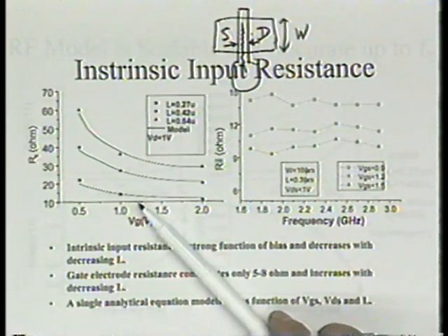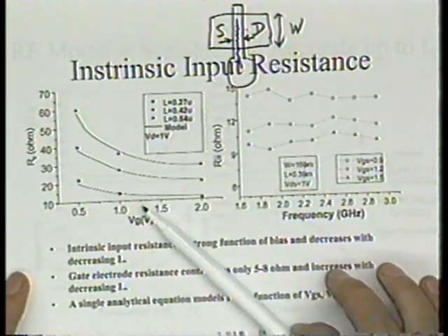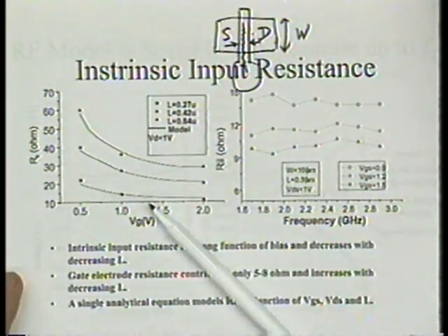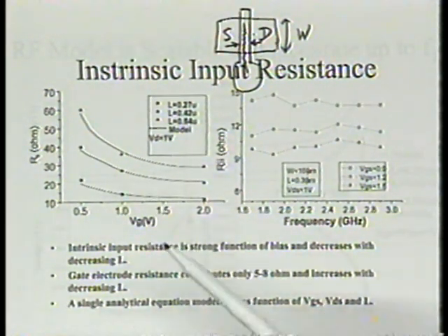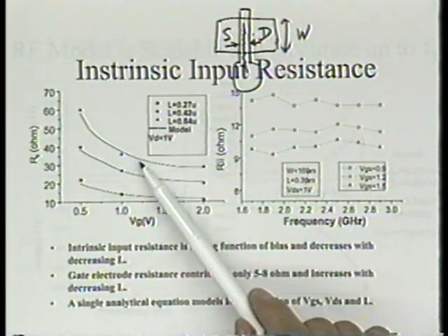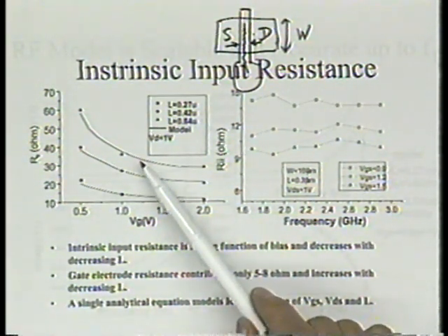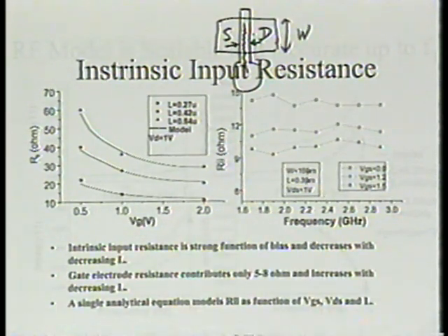But let me put it this way. As a result of the gate impedance, the transistor loses more performance in the long channel transistor due to that effect than the short channel transistor. Okay, going to a short transistor makes this gate impedance effect less important.